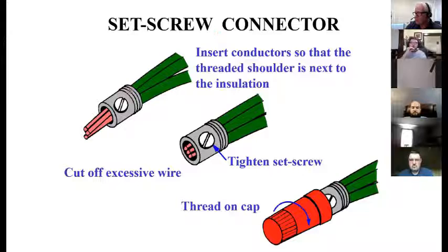Screw-on connectors. You strip the wires and you put it in this thing and you tighten down the set screw, and then you just cut this off. And then I really like this. This thing fits over it and threads down on that.